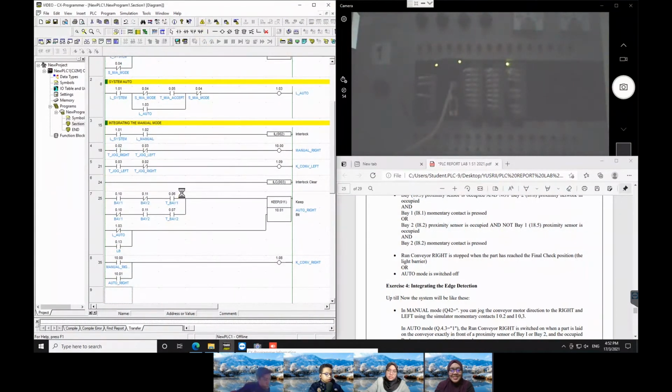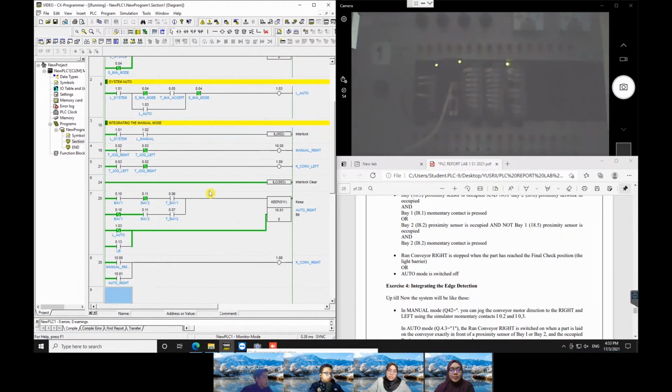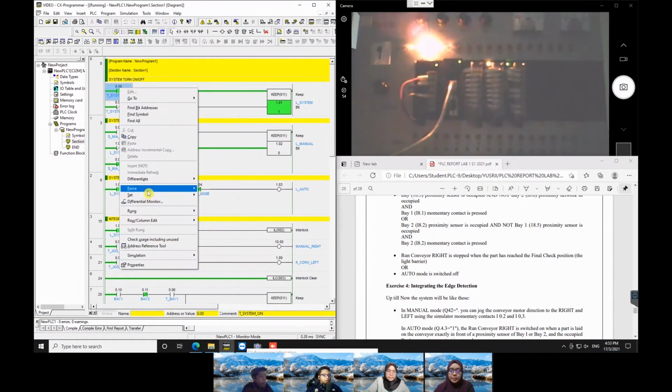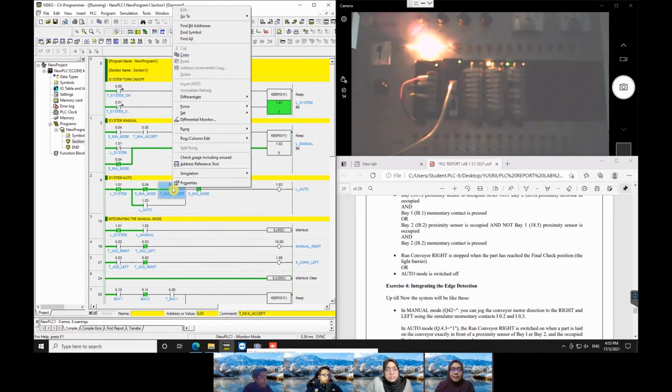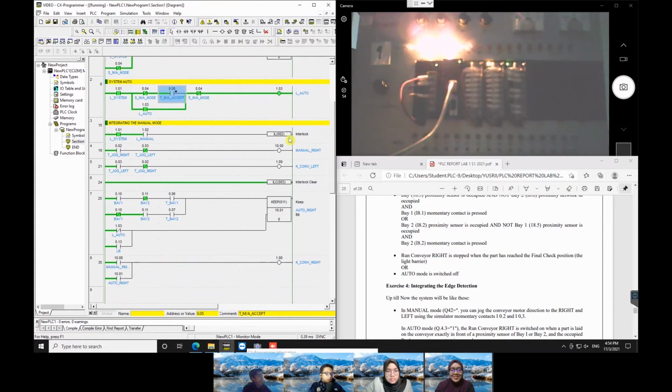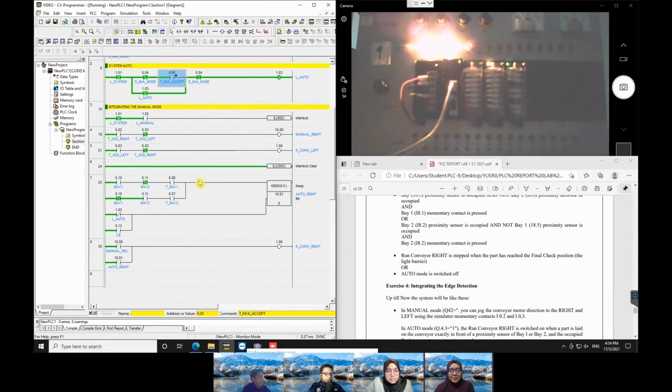First, we need to work it online. Then we will transfer it to the PLC. Before we start, we need to turn on the PLC system. Since we use a push button, we need to switch the system on. Since we use auto mode, we need to accept the system auto. Then B1 will sense the item, so we need to turn on B1.